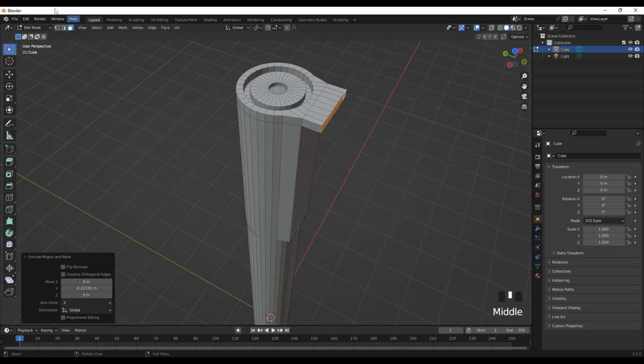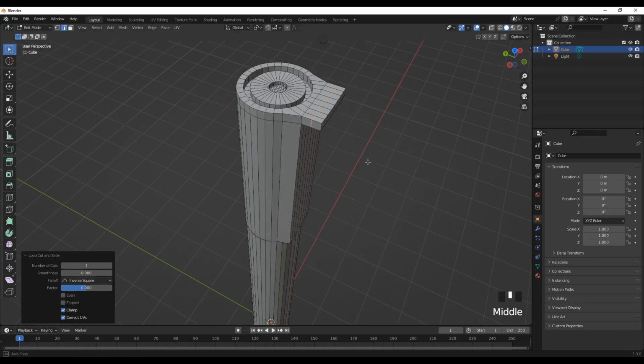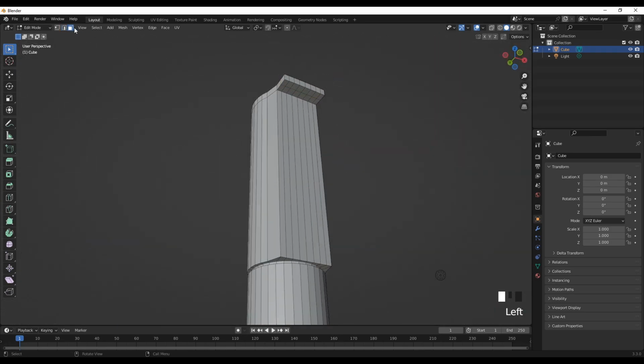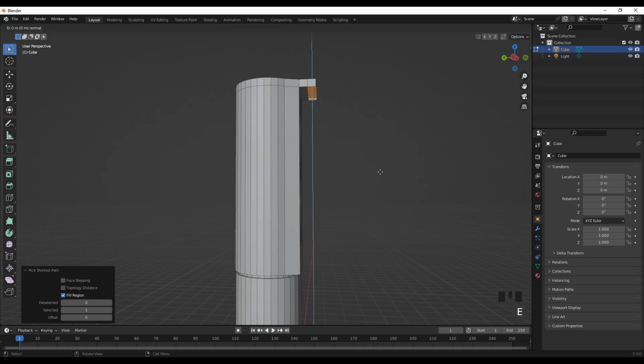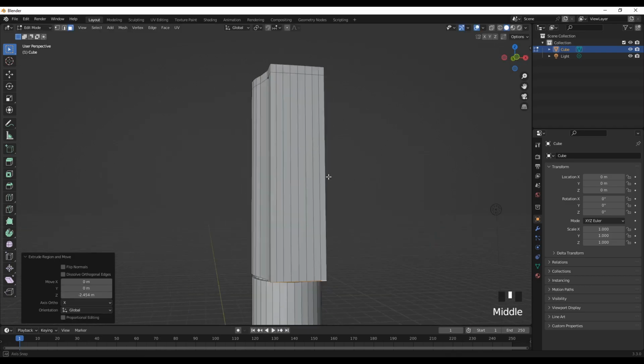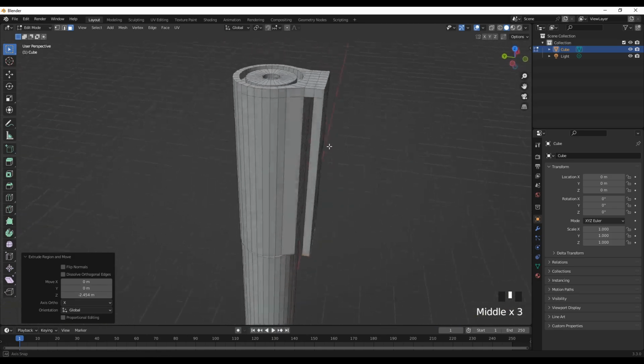Okay, now go to the line tab again. We can subdivide this. Control R. This is okay. Select the bottom part to extrude to create an extension. Now extrude this along the Z, somewhere like this. So this looks basically the handle of the top part.